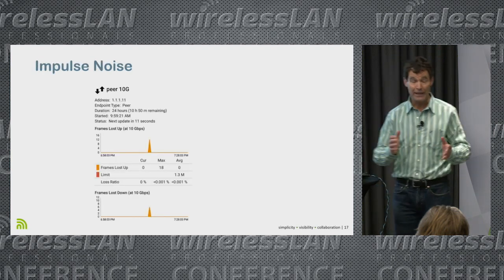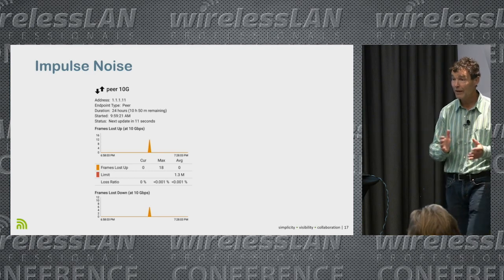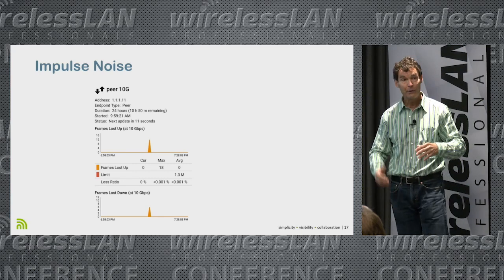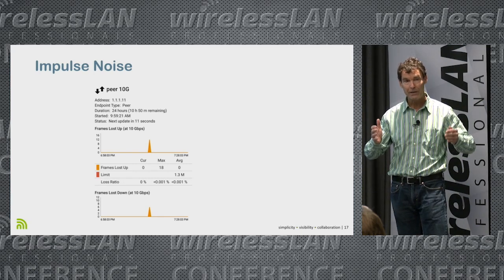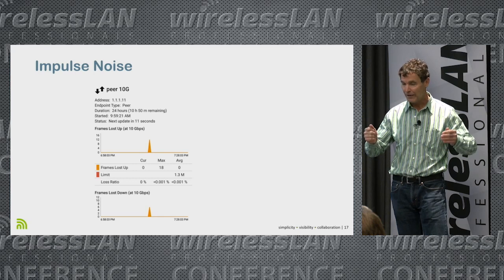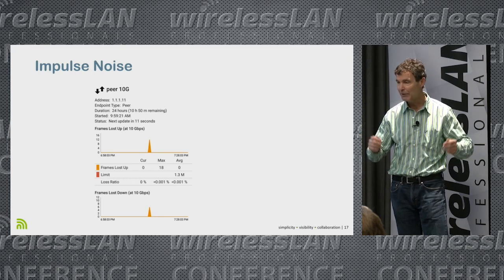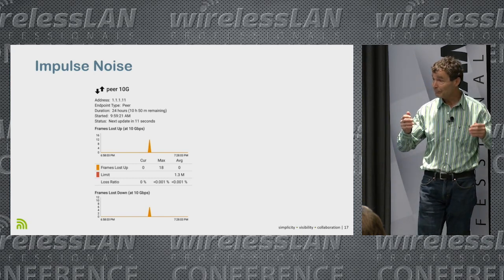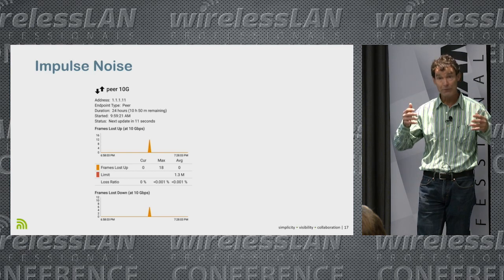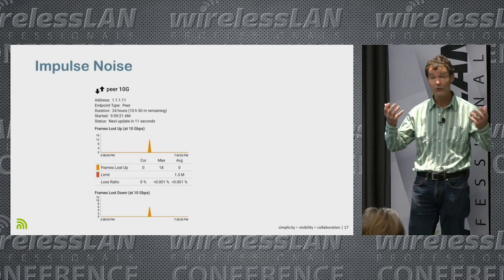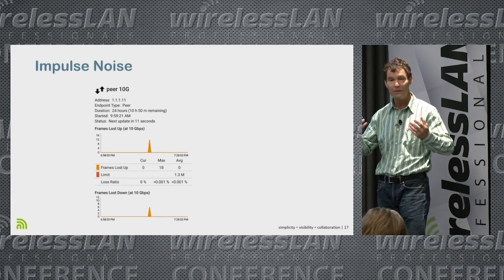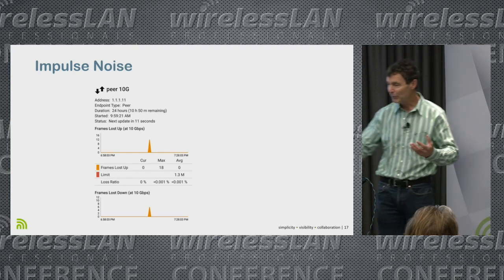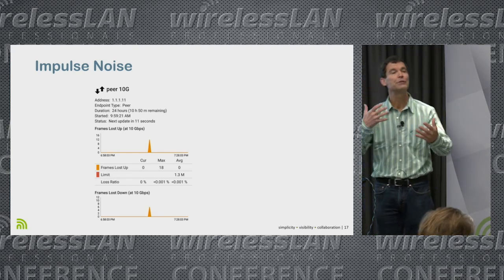So the next thing to look out for in NBase T is impulse noise. This one actually we backed into about 4 or 5 months ago when we were preparing the new product. We run these 24-hour 10 gigabit line rate performance tests, and we were running over Cat6 cable, Cat7 cable, and they're very deterministic. It's literally every frame sequence numbered, accounted for, FPGAs on both sides doing all this. And we were just seeing these crazy spikes of loss, and it drove us crazy for a couple of weeks, and couldn't quite figure it out. We assumed it was something in our hardware.